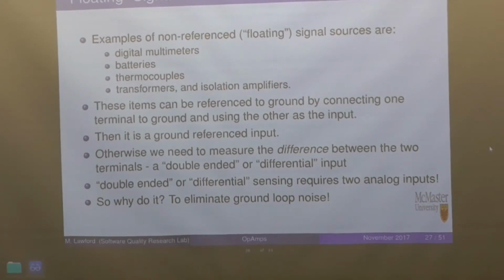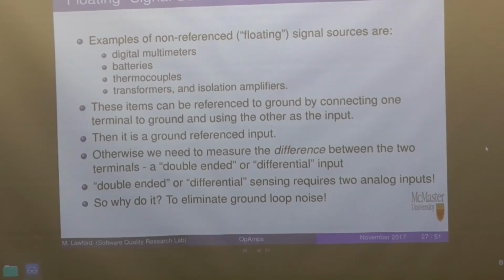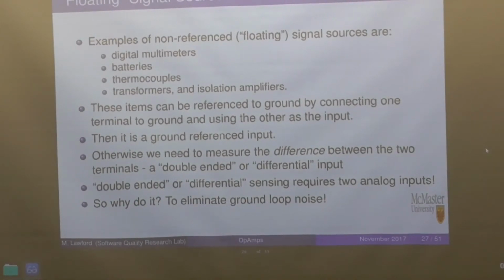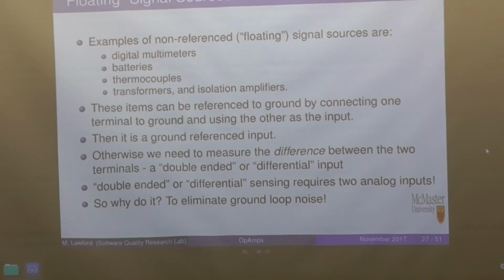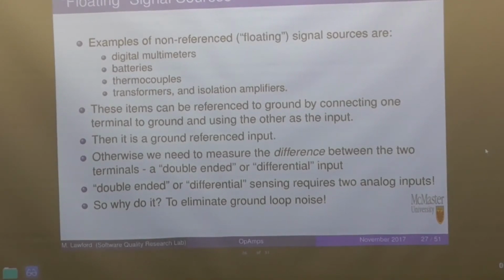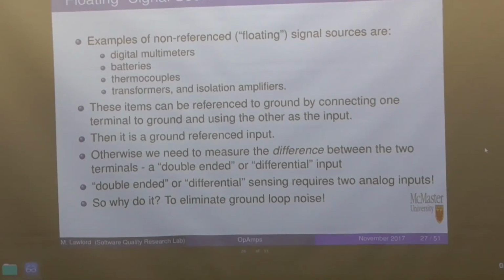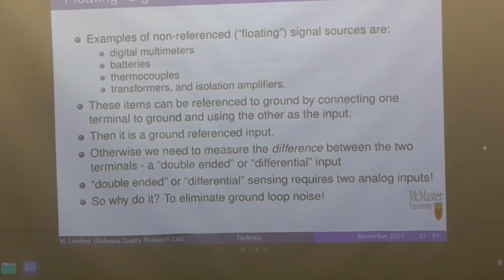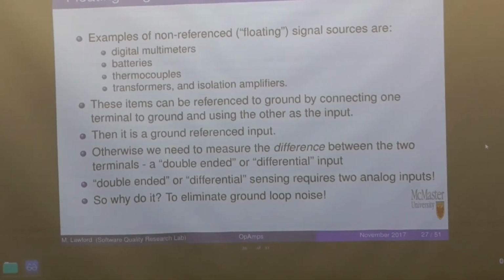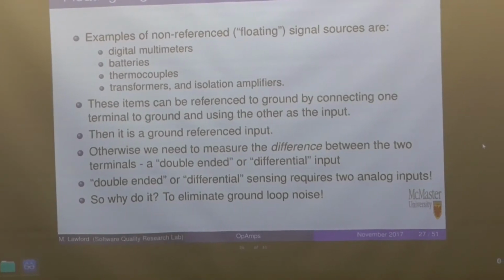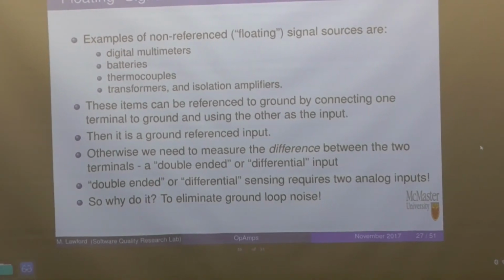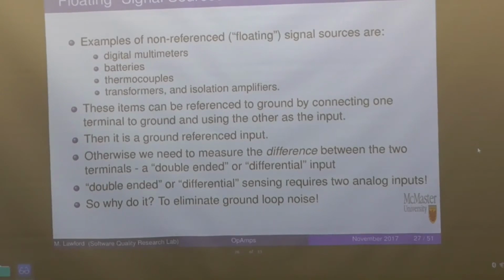So, we do this to eliminate ground loop noise, right? If it's floating, then it'll be referenced to whatever the ground is for the thing that it's connected to. Obviously, it's not good to leave it floating, but if the intention is to leave it like, have it connected to something.